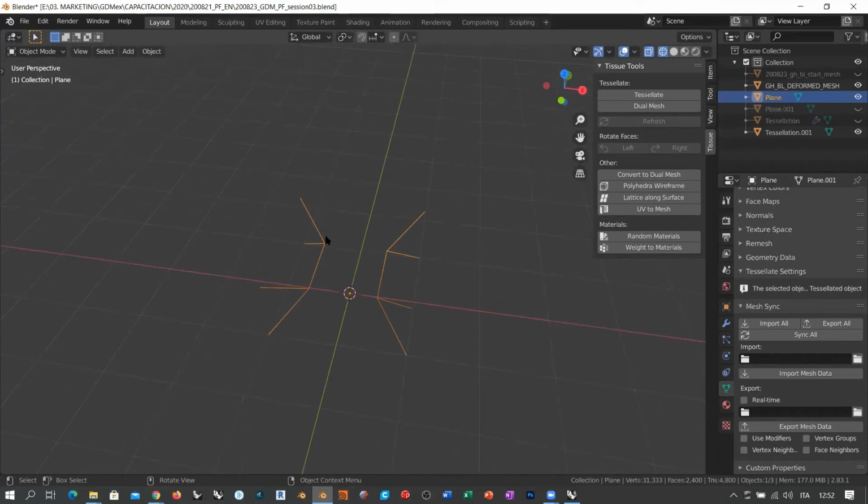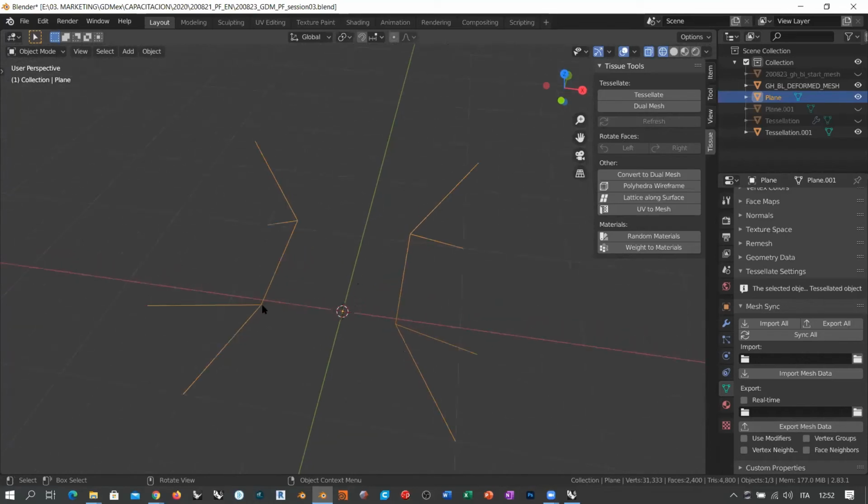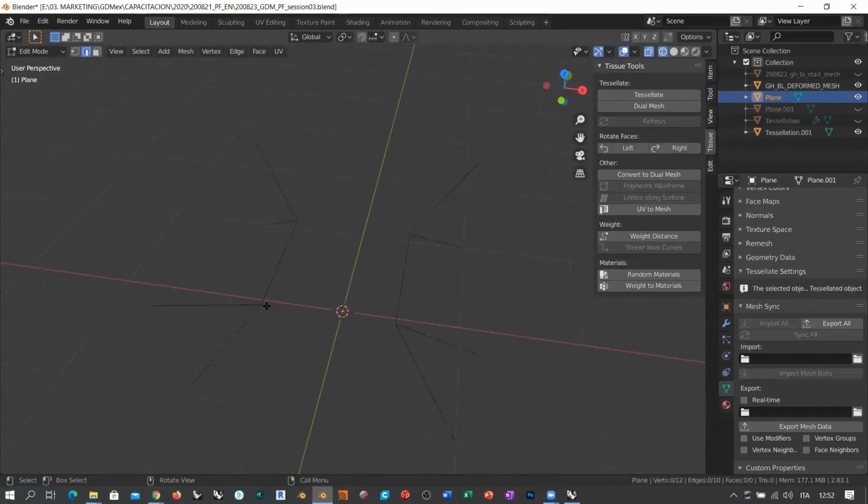So say I don't want a square anymore. What I want, for example, is I go into edit mode, select the vertices, take these two here, create the edge, and then Control R, like loop cut, and create a vertex here at the center. And then I have two separate edges, 1 and 2, and I also can obtain this and this.